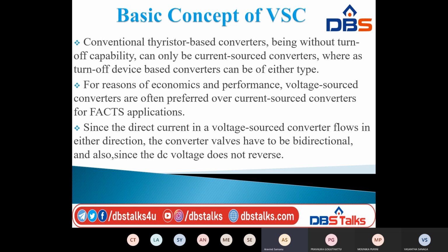Voltage source converters are often preferred over current source converters for FACTS applications. Since the direct current in a voltage source converter flows in either direction, the converter valves have to be bidirectional, and also the DC voltage does not reverse.